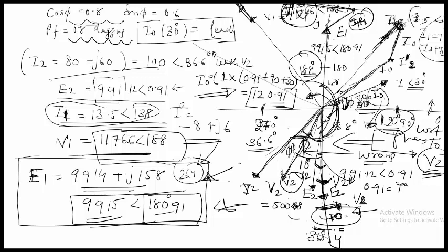So that was the reason why we had taken that, and again it will make no difference, because if you are considering it with the x-axis, whatever was given, it was 30 degrees. But at the same time, while you are drawing the other values, it was necessary to convert the value of I1 in terms of how it was seen with respect to V2, or with respect to the voltage on the secondary side. So that was the reason, if you wondered why this was changed here.